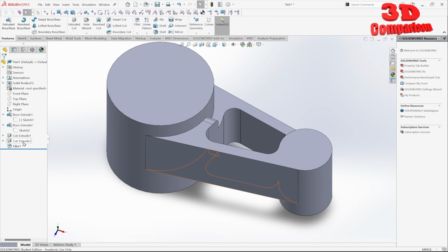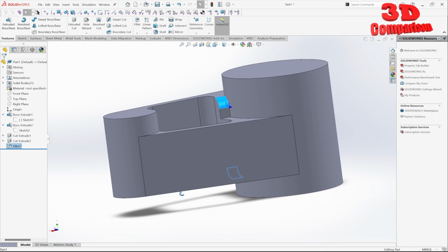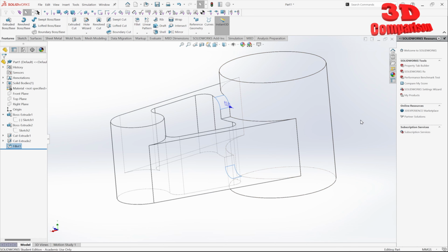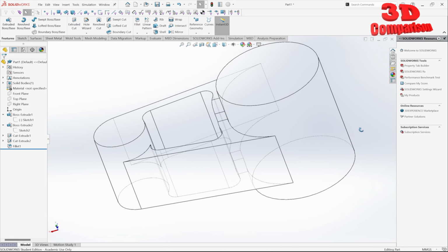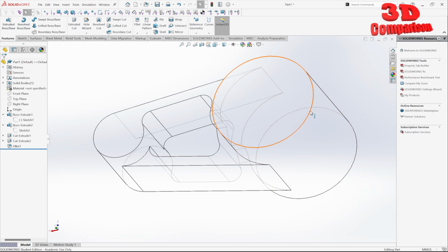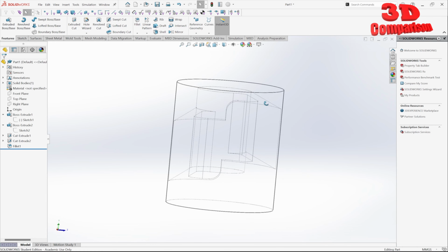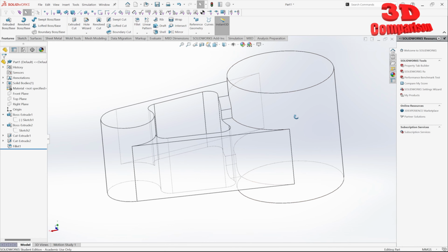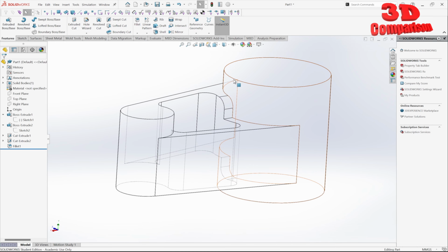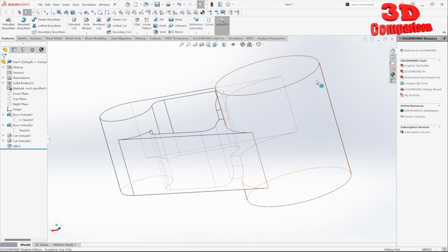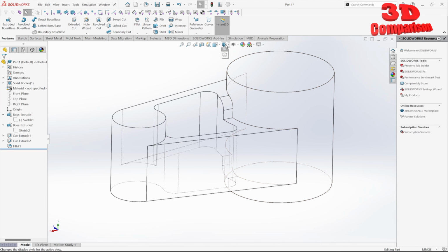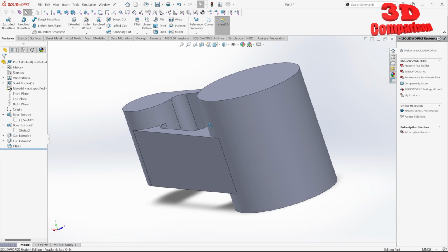And afterwards, we're going to have those cuts. And as we can see, the fillet can be created over here without any problem. If I go within the wireframe, I will see that edge over there, but that's actually the edge. As I rotate, that will also move, so it will not always remain in the middle like the one in CATIA. And this is the main difference why there are some topological problems within Part Design for CATIA, especially when using circles that are extruded, because those shouldn't have additional lines since we are modeling this within solid bodies.